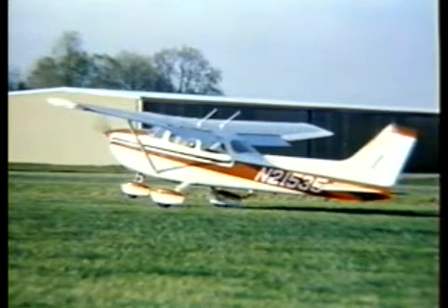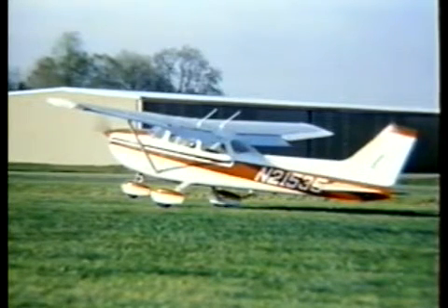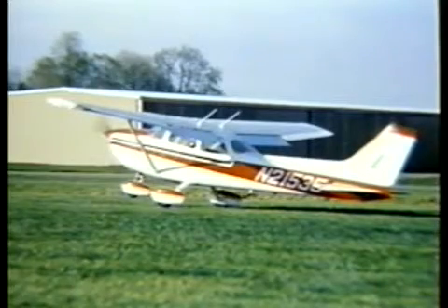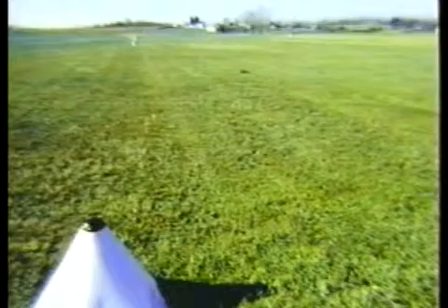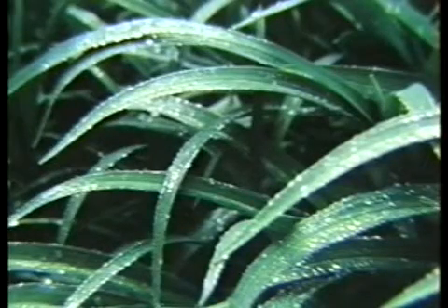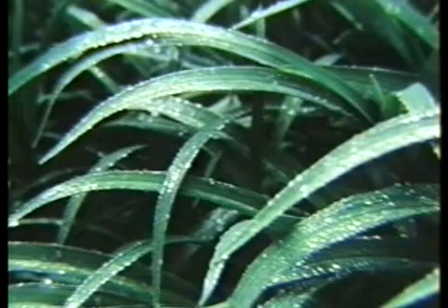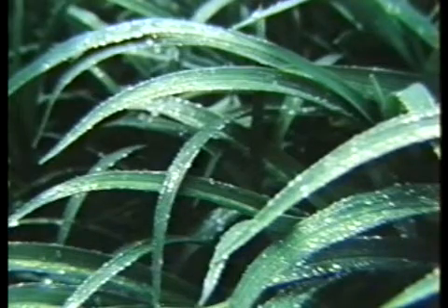Now, landing on a grass runway is a great way to preserve your tires, but remember, grass is also a much less effective braking surface. Wet grass or frost-covered grass is even worse, so beware. Also, to avoid surprises on your landing rollout, be sure to check your brake pedal pressure before you enter the traffic pattern.